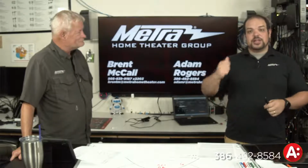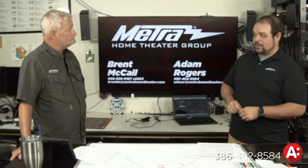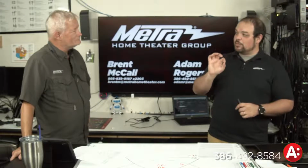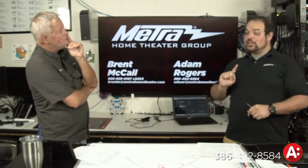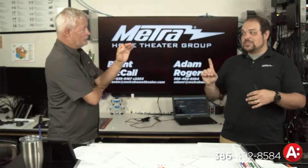Here's the deal. You plug in a non-PoE device. Here's what happens. The system will send out a very small amount of voltage. Not harmful. It's 2.7 volts down that line. And what happens is it's looking for resistance on the other end. Now, a specific resistance value. Exactly.